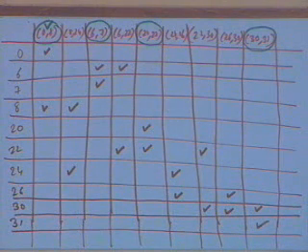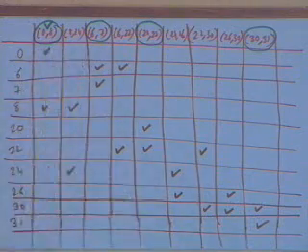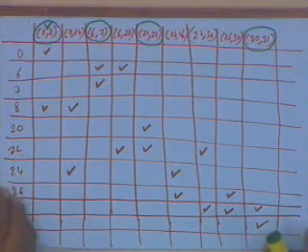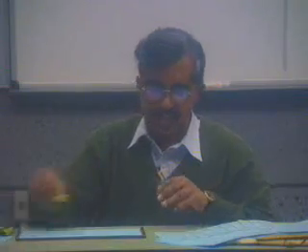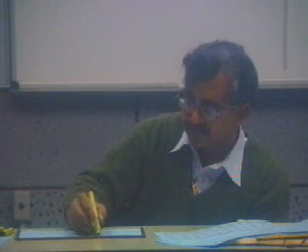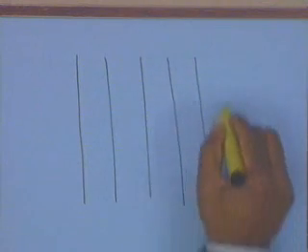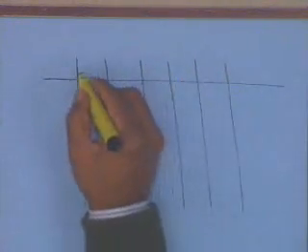Okay. So now I can draw what is called a reduced cover table. In my reduced cover table, I don't have to bother about the minterms which are covered by them, not just the minterms which have made them essential, but even the other minterms which are covered by them. Because after all, I have already covered those minterms, and I don't really have to bother about those minterms. So I will draw another cover table. Now this particular cover table will have fewer columns and rows. I will now draw only non-essential ones.